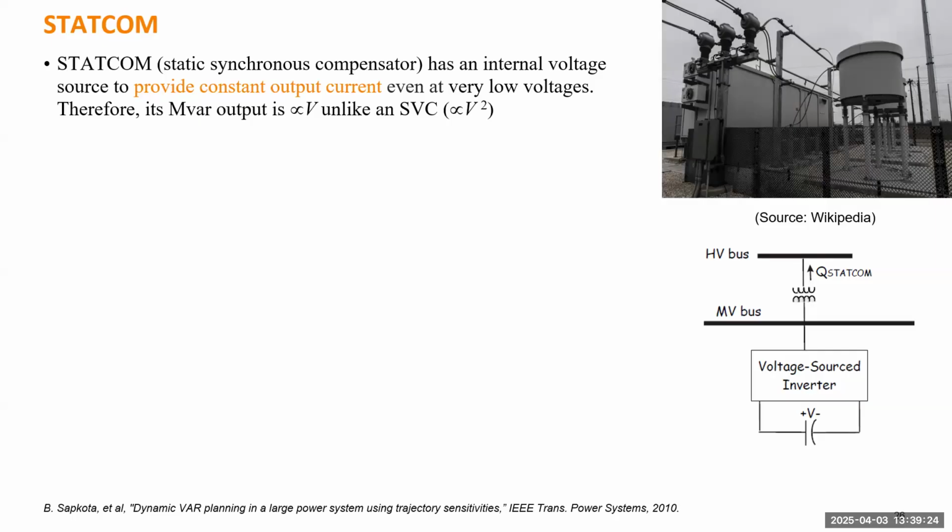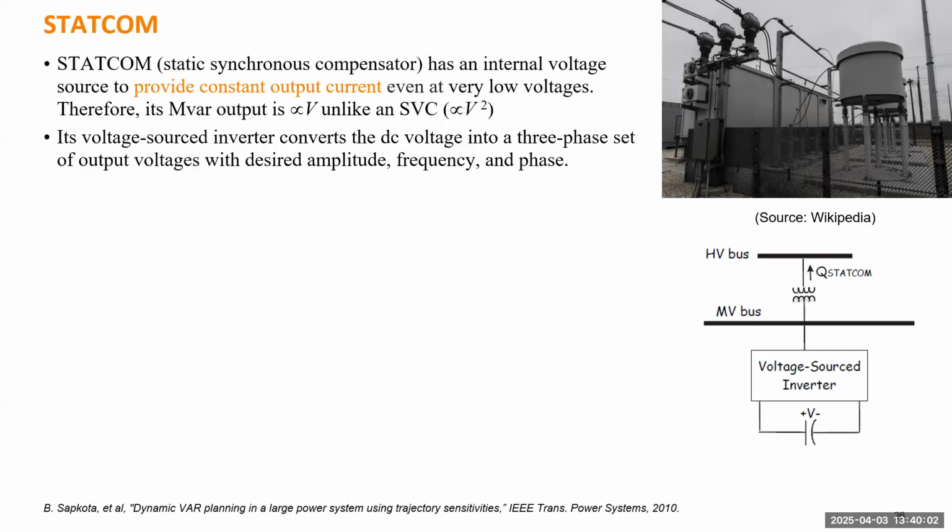So the question is whether the manufacturer or operator really desires them to operate as a STATCOM. Operating as a STATCOM means that under some conditions or in some operation mode, the main purpose is to provide reactive power, to provide a high inductive current to the system, but not a capacitive current. But that may not be good for the life or condition of these renewable energy resources. So utilities do place dedicated STATCOMs there. It can be very expensive.